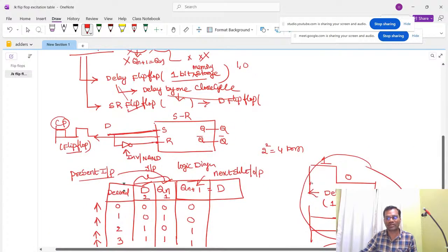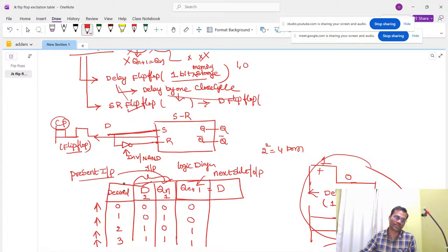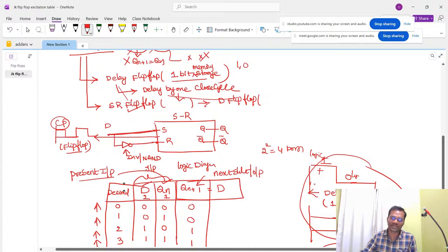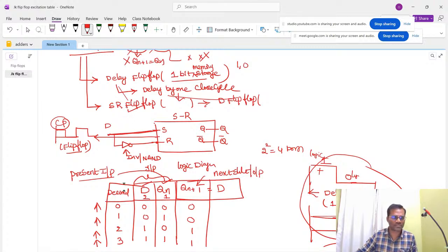So this is called the positive cycle or the negative cycle, or you can take this as logic 1 and this as logic 0. The complete flip flop output should be delayed with a time period of 1. Then these kinds of flip flops are called D flip flops.